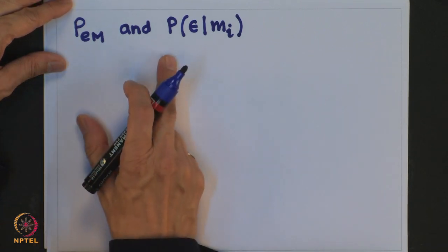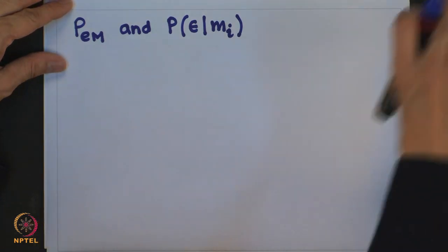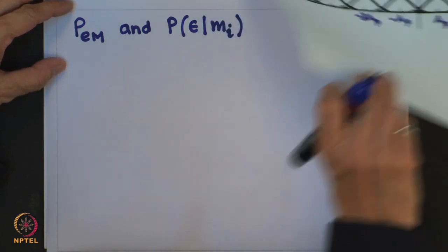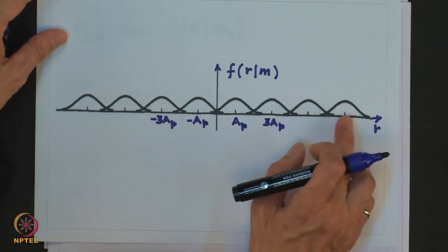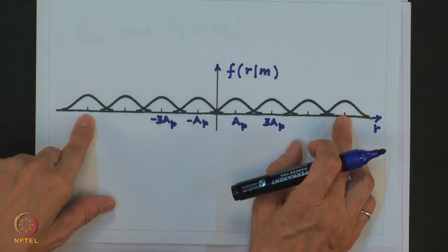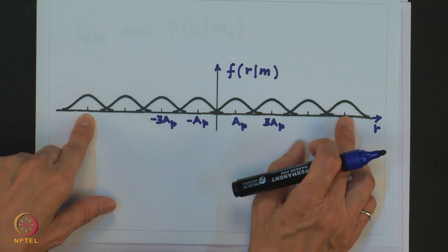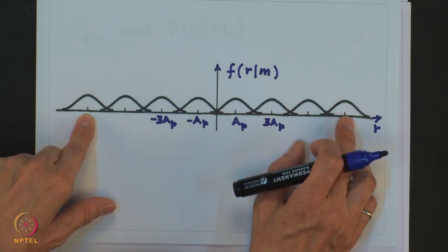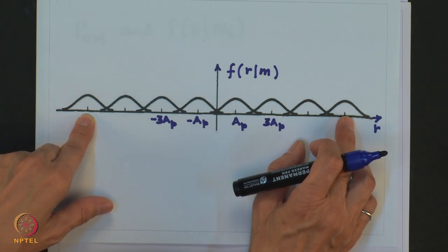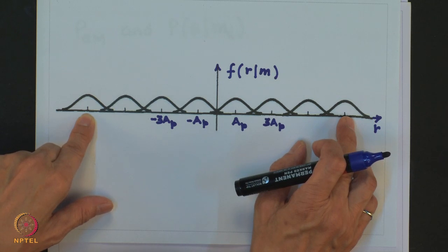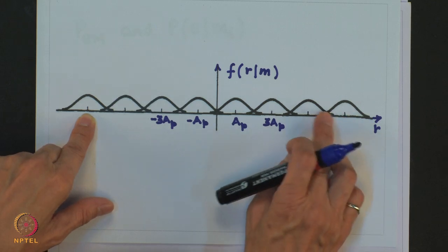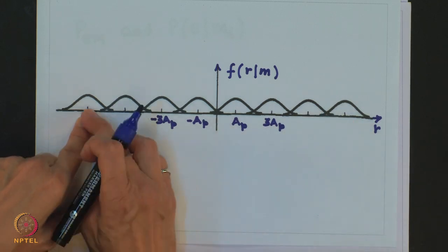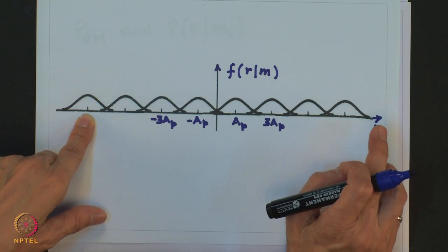So, to do this, observe that for the case of two extreme symbols which are represented by plus minus M minus 1 Pt, error probability calculation is similar to the binary case which we have studied earlier, because they have to guard against only one neighbor. For this it is this side, and for this it is this side, correct?